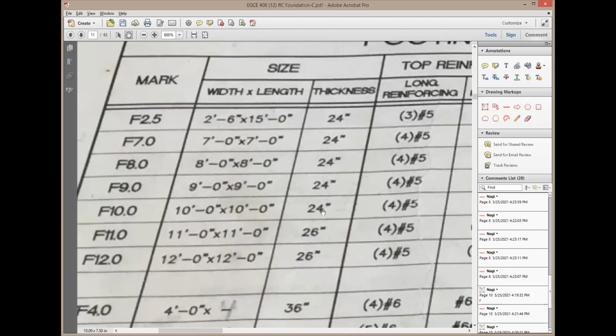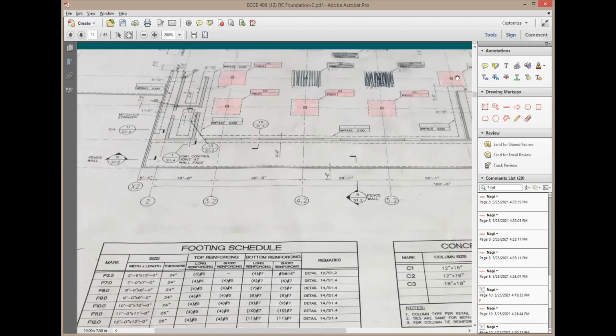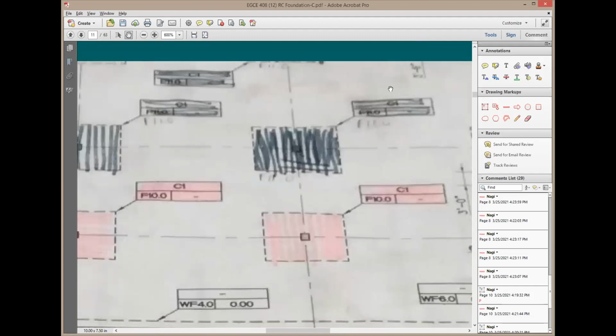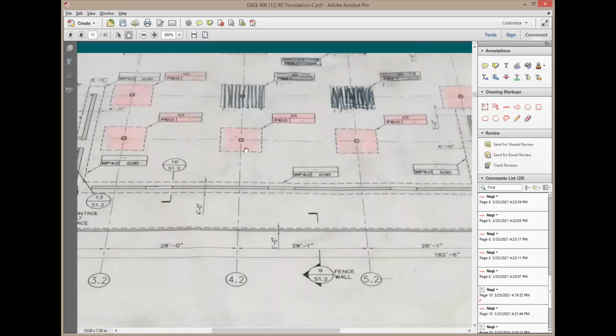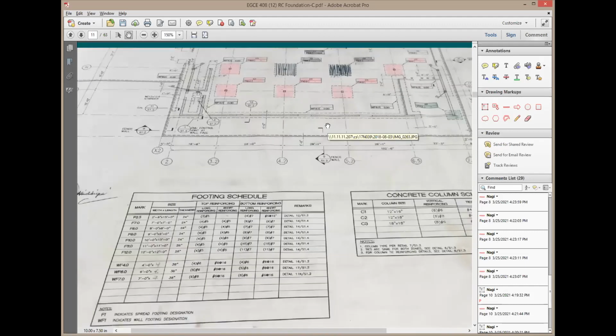And you see here the thickness of the footing is 24 inch. We designed this thickness. We came up with it, and this gave you the total thickness of the footing. So you see here we have plenty of footings, and that picture was taken at the site. The contractor would like to do this in one shot, right? So they put the concrete here in one shot, and this shaded or hatched area, he'd like to do in the second pour. So we said, okay, it's up to him. We don't care. He can pour it in any sequence he wants.